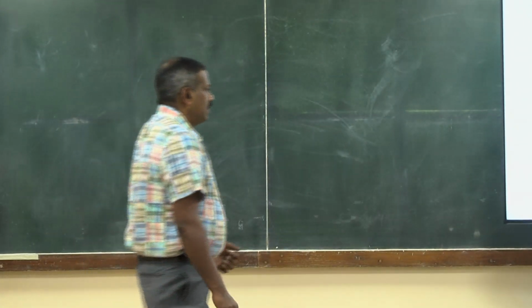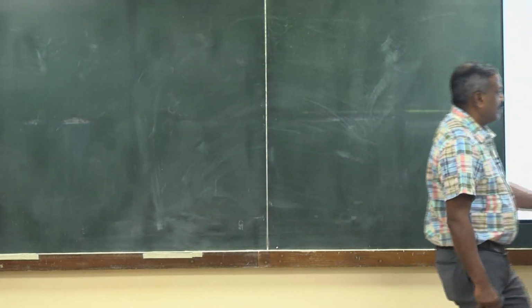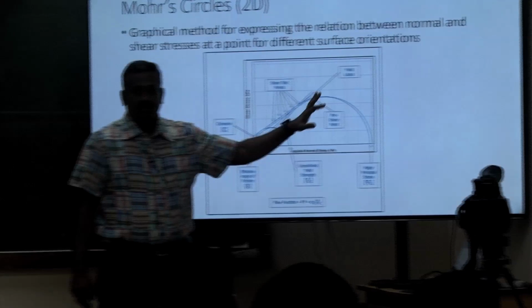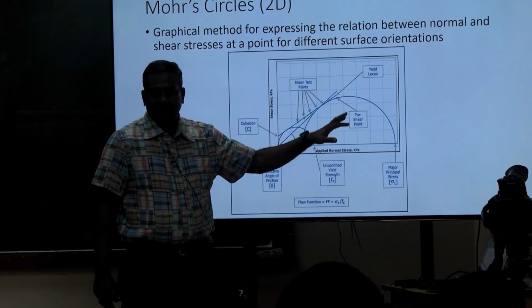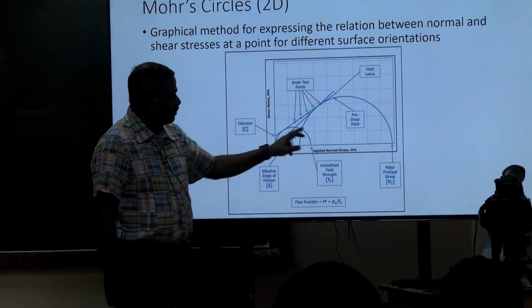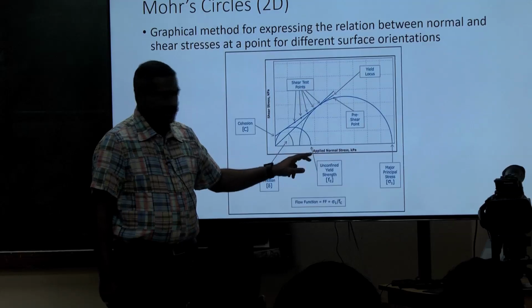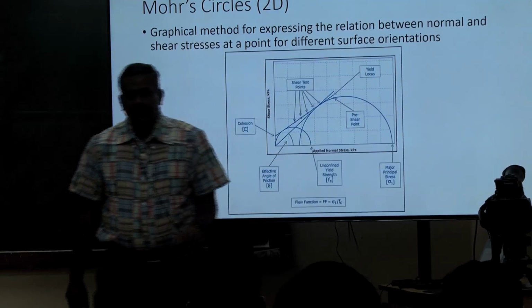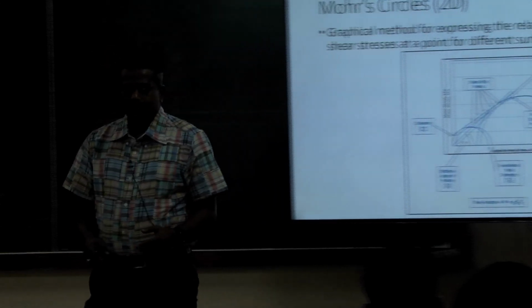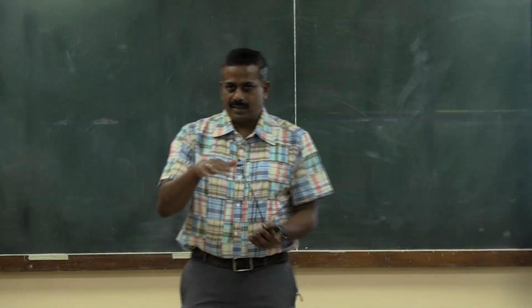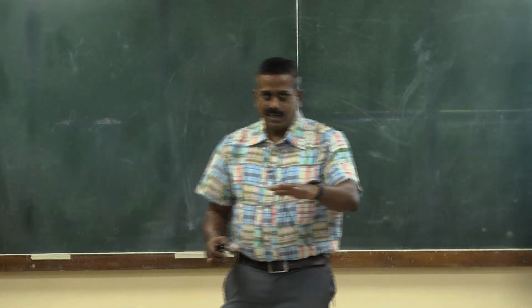So then, using those points and the yield locus, we draw two more circles. You can draw more than two, but primarily we draw two more circles. I am showing only half of this here, though it will be a circle. But when we talk about powder flow, at least it is in 180 degrees, right, it is a plane. So we take half of the circle.